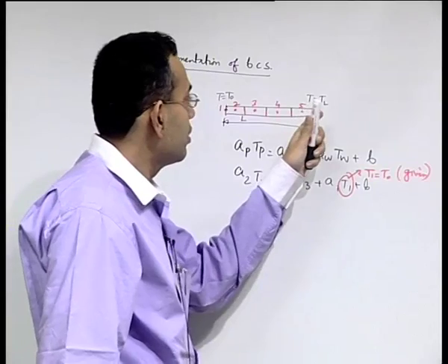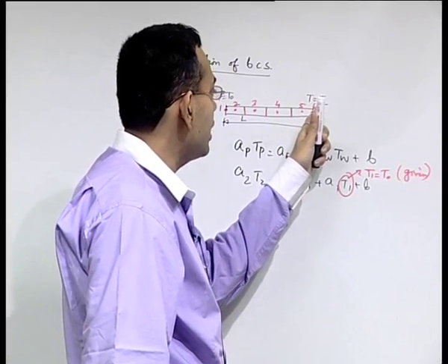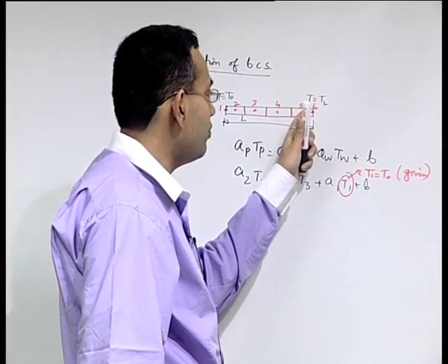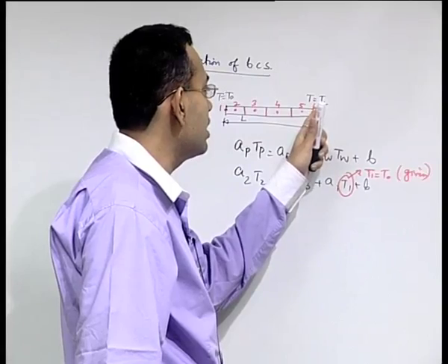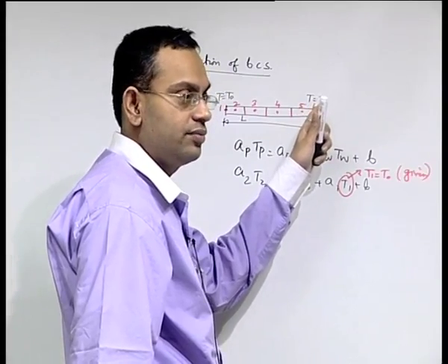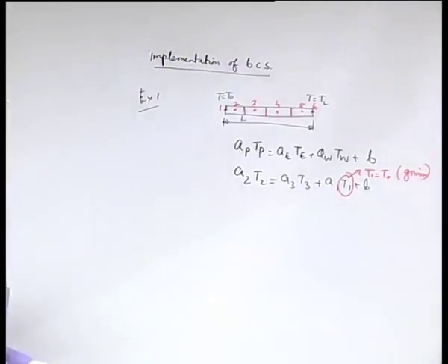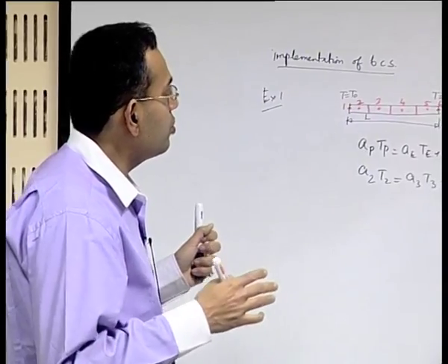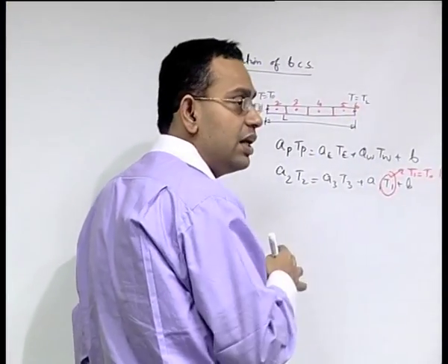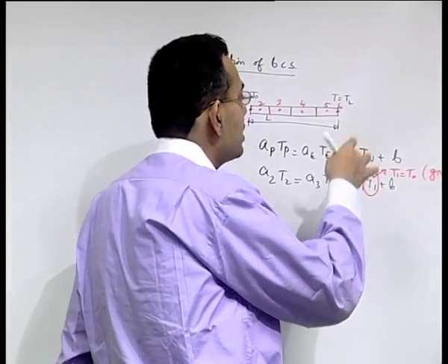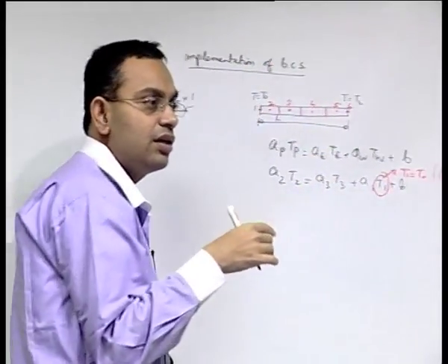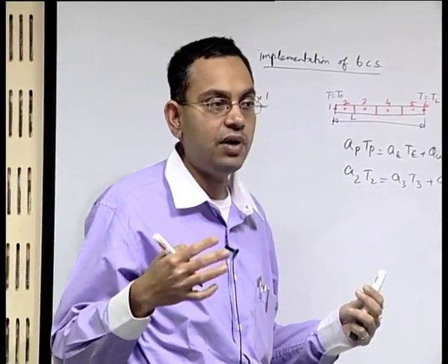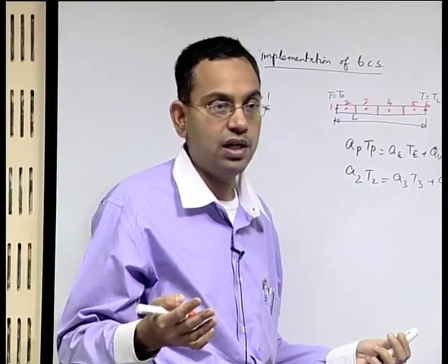Similarly, for the given temperature boundary condition at 6 you can write the discretized equation for the grid point 5 and at T6 you substitute TL, that is very straightforward. If you are not willing to make this substitution specifically but still you want to impose a given temperature boundary, you can use the penalty approach that we have discussed in the finite element method context.